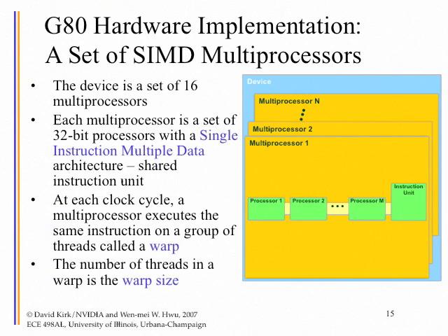And what that tells you is what the hardware really does is it breaks down the block into multiple warps, and each warp will actually independently use the instruction unit. Okay, that's really what's happening in the real hardware. So only when the execution diverges within the 32-thread warp unit do you suffer the performance penalty.